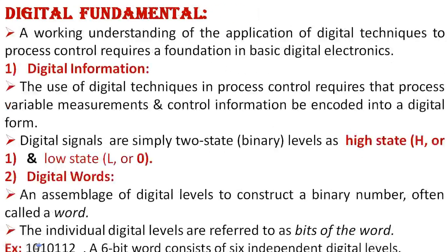Next concept is digital fundamentals. A working understanding of the application of digital techniques to process control requires a foundation in basic digital electronics. The use of digital techniques in process control requires that process variable measurements and control information be encoded in digital form. The digital signals are simply two binary labels, a high state and a low state. So the high state is denoted by capital H or 1, and the low state is denoted by capital L or 0.